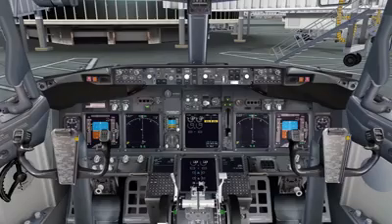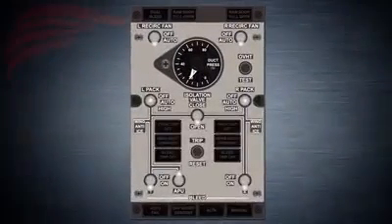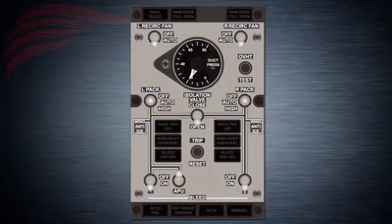Bleed air temperature is cooled in a cross-flow heat exchanger referred to as the pre-cooler. Ideal bleed air temperature should be between 199 degrees Celsius and 229 degrees Celsius, and it is achieved by exchanging heat between cool engine fan air and bleed air. An over-temperature mechanism protects the pneumatic manifold from receiving bleed air that is too hot. The threshold temperature is 254 degrees Celsius, after which, if an overheat condition is detected, the bleed air shutoff valve is closed and the cockpit bleed trip off light comes on.